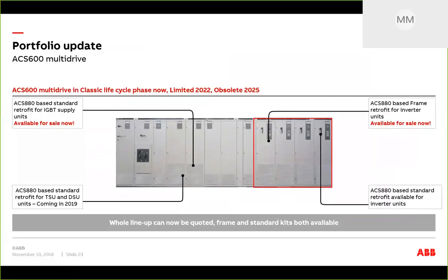What's highlighted in red there is 4 small sections. Replace the disconnects, even replace the doors to show the new HMIs, replace the inverter, and it all comes on like a unistrut frame solution. So it's meant to fit in a 400 or 600 millimeter cabinet quickly.